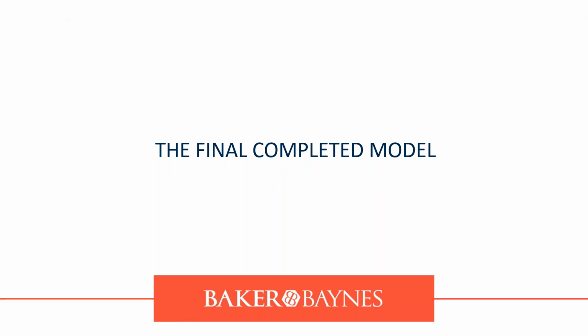So I've repeated all of the same steps that I've showed you throughout this entire webinar, okay? I've created the corridors in Civil 3D, I've done the targeting, I've done the long sections, I've done the assemblies correctly, because the assemblies, if you're doing a complicated road, like with a median and stuff like that, you need to go and probably fix that first and then model in Civil 3D because it doesn't translate that well from InfraWorks. To create the final surfaces, like the whole process that you would normally do in your Civil 3D course or as a civil professional. I followed all of those. I brought all of them together, and I've also added elements that I've showed you in previous webinars of inserting trees, cars, people, those type of things. So enough of suspense. Let's have a look at how it looks here.